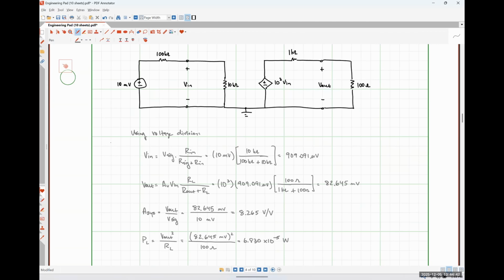So choosing an amplifier that matches the parameters of the external things that you are going to connect to it makes a big difference in the overall performance of the amplifier itself. So going back to what I had mentioned earlier, when we have a voltage amplifier system, we typically want the input resistance to be as large as it can possibly be, and the output resistance to be as small as it can possibly be, because that's going to make the system gain be as close to the amplifier's gain as we can possibly get it.